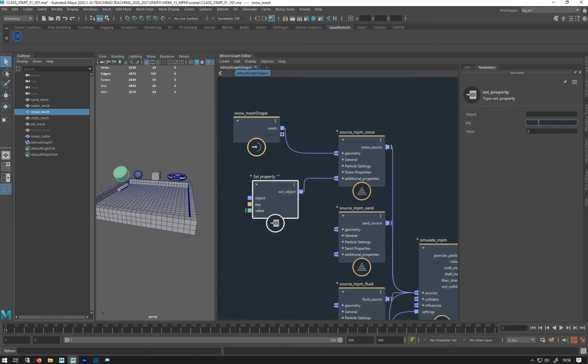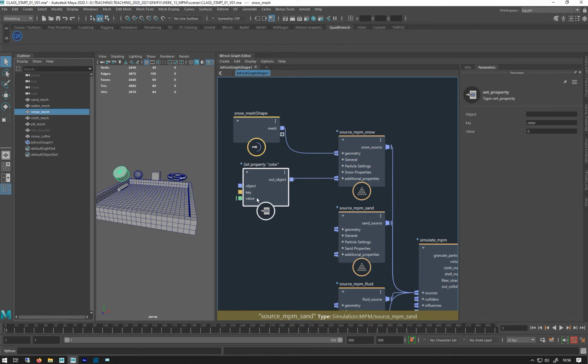And that is called C, oops, not capitals, COLOR, so color spelled in the American way. And then we have to give it a value which makes sense for a color, which is an RGB, so that's 3 numbers. So we have to just right click our value, go value type, and we say math float 3, like that. So now we have these 3 values.